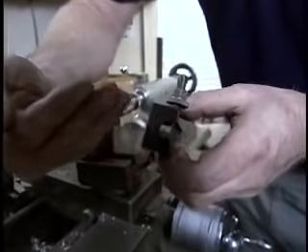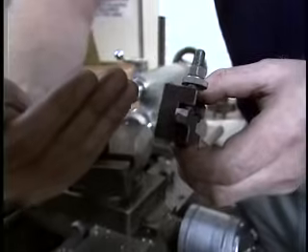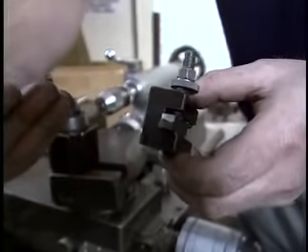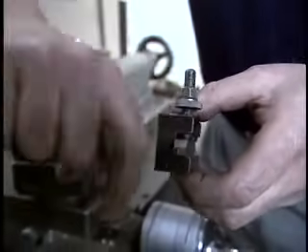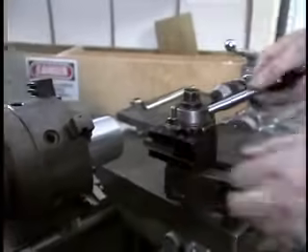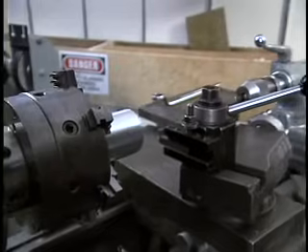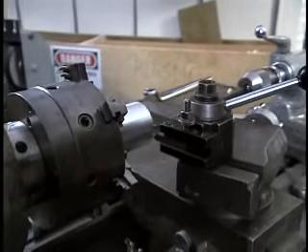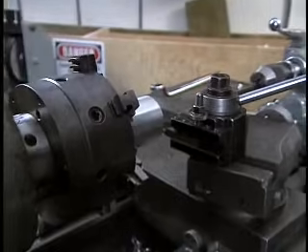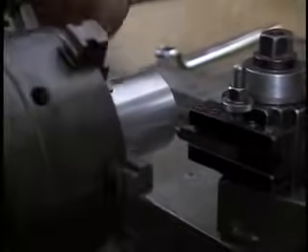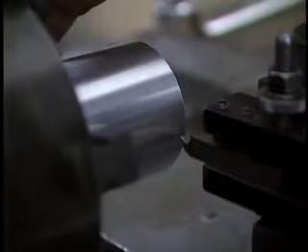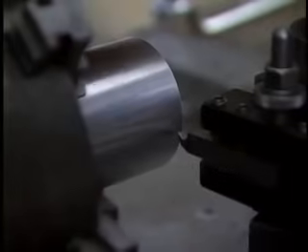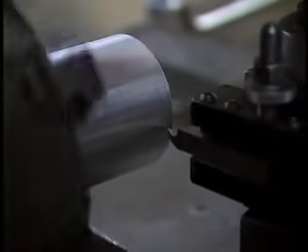You can see that the top of the tool is tilted to an angle like this, so that as you're cutting in this direction, the chips come down onto the tool and slide off the tool nicely. Start by bringing the tool close to the part, then turning the chuck. Doing this to make sure there are no interferences either between the tool and the part or between parts of the chuck and the rest of the machine.